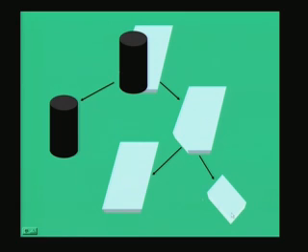If A is the left hand object here, which is the larger rectangular parallelepiped, and B the smaller one, then I can have A minus B. Of course, you need to position the B suitably such that you know which part is to be taken out or truncated. So, this is an example of how constructive solid geometry could be used to generate complex structures.